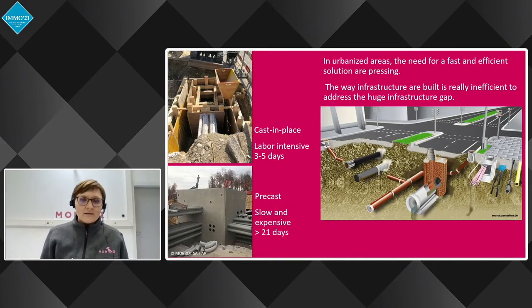And when you construct a road like this, every 15 meters in urban areas and every 250 meters in extra urban areas, you have concrete elements, what we call cable chambers, that enable technicians to go underground and use or adapt utilities such as electricity, energy, or water cables.